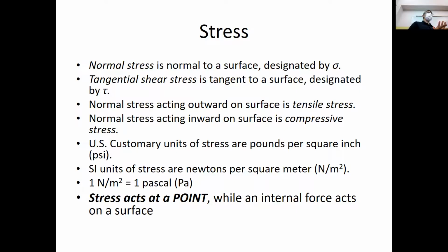With the normal stress, we need to distinguish between a pull or a push, tensile or compressive. When I am pulling or acting outward on a surface, that's a tensile stress, and we usually give it a positive sign. When it's pushing on a surface, it's compressive, and we use a negative sign to describe that.